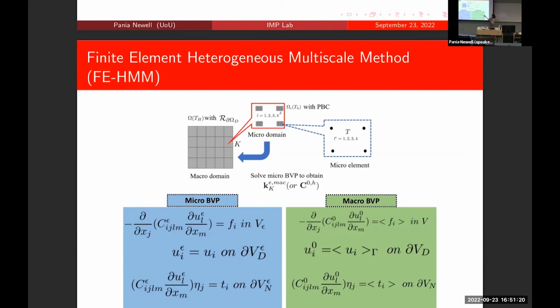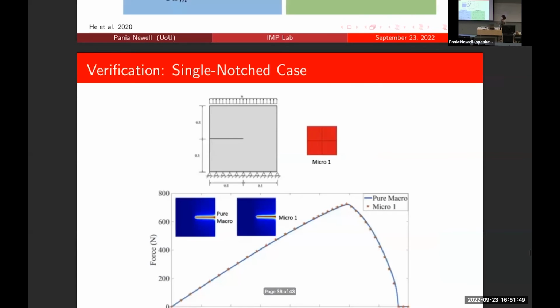So we needed to use this homogenization, but the homogenization is only to give us the material constitutive parameters. That's the only reason that we are doing it. And we get the constitutive parameters, so we don't need to know them at the macroscopic level. We have a bunch of SEM images, microstructural images, and we can run this homogenization to extract the properties. And at the macroscopic level, to capture the fracture evolution, we simply use phase field.